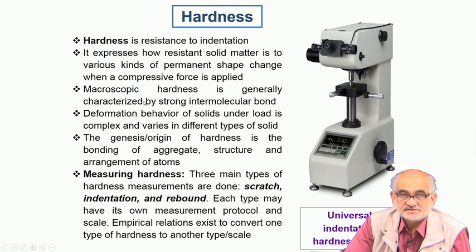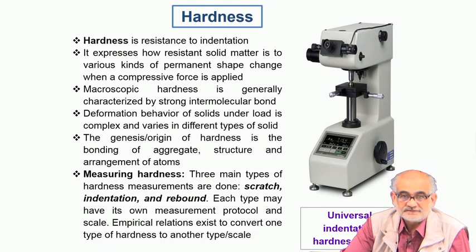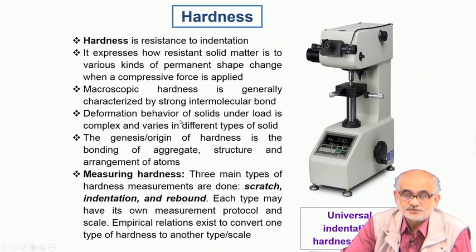The hardness can be ascertained by whatever changes the activation makes onto the surface by macroscopic observation. We call it macroscopic hardness. So typically the so-called Brinell hardness tester would be one such device, or the rebound hardness by Poldi and so on. So essentially they test the intermolecular bond strength of the molecules or the atoms at the surfaces. But then we must realize that no matter what kind of load we apply, we actually can always have certain derived components which could be tensile in nature or shear in nature and so on.